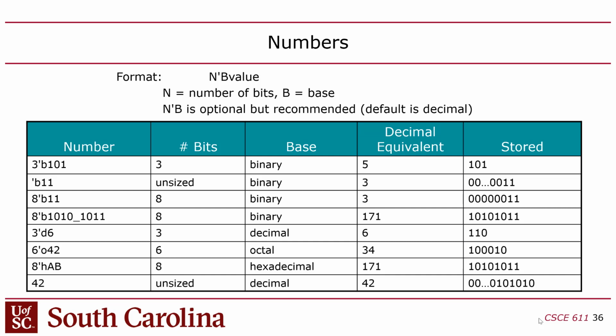So there's a way to do that in Verilog, and if you're a careful Verilog programmer, which you should be, because otherwise you can run into some weird errors, unexplainable behavior sometimes. Whenever you have a constant, you should specify its width in bits, right? So the way you do that is use the apostrophe. For example, you'll say 3 apostrophe, and then you put your constant, and that means it's a 3-bit constant. Whatever follows that is the value, but it's going to be in 3 bits.